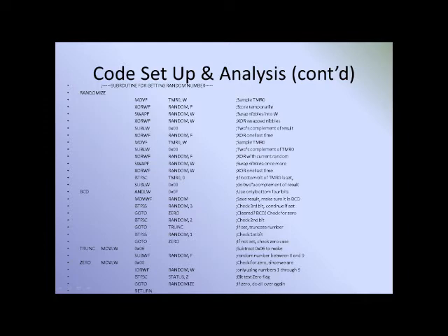Thus, literal 00 was IOR'd with random in order to not corrupt the generated random value. This also allowed the program to check the Z flag in status to determine whether random was 0. If the Z flag was set, the randomized subroutine was called again. Otherwise, the generated value was definitely between 1 and 9.